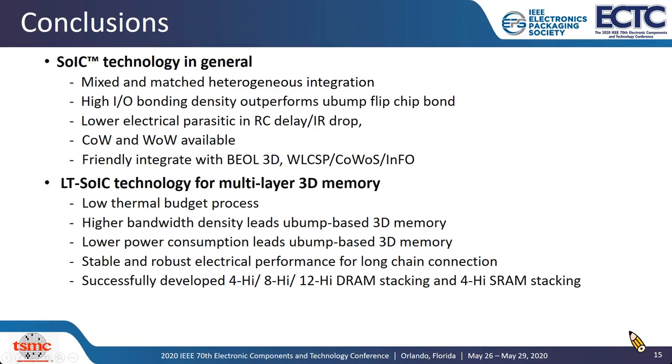Here are the conclusions for SOIC technology in general and low-temperature SOIC technology for multi-layer 3D memory. SOIC technology allows mixed and matched heterogeneous integration and can offer much higher I/O bonding density with lower electrical parasitics in RC delay and IR drop. It is also available for both chip-on-wafer and wafer-on-wafer processes, and is very flexible to integrate with back-end 3D IC such as wafer-level CSP, CoWoS, and InFO.